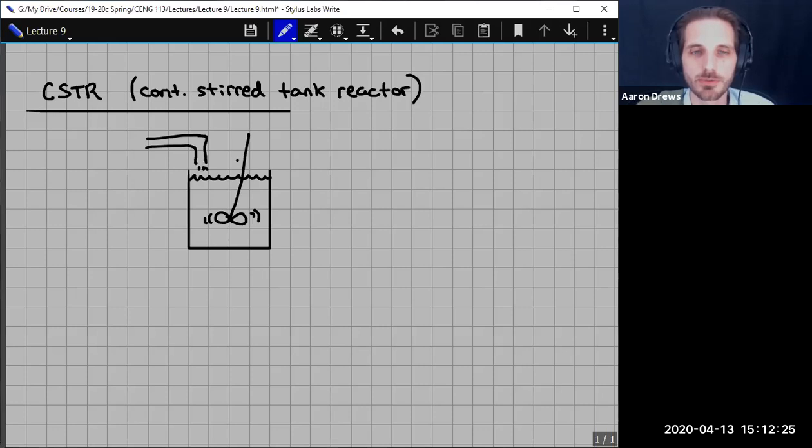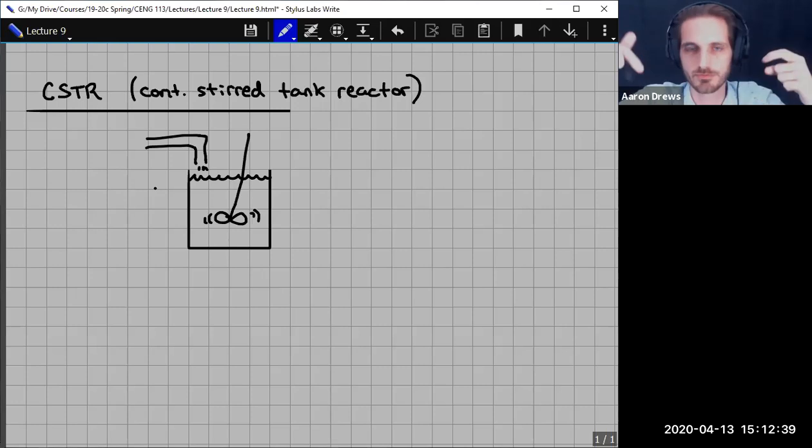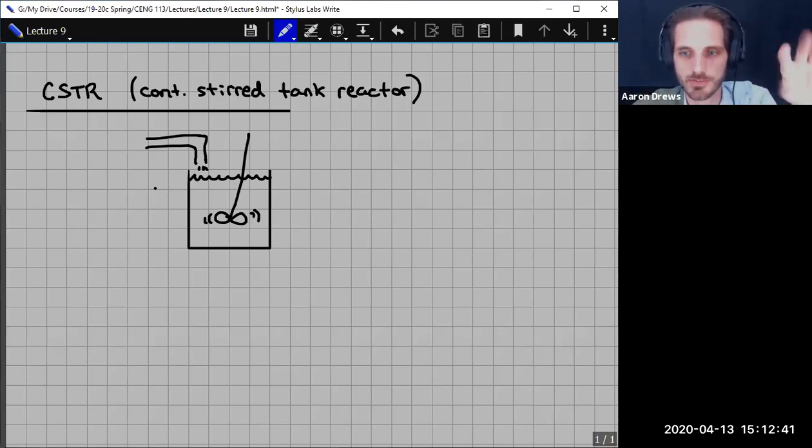Almost every system that we would deal with in here is only going to have a single inlet, because a lot of reactors are designed to only have a single inlet and a single outlet. It's hard enough to manage the temperature profile and the mixing inside if you don't have a bunch of ports, holes drilled all over your reactor and stuff coming in through there. So a lot of times we're going to be dealing with a single inlet and a single outlet, because that's how a fair number of reactors are actually designed.